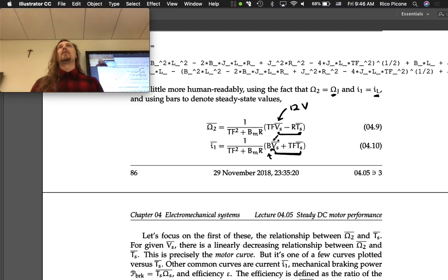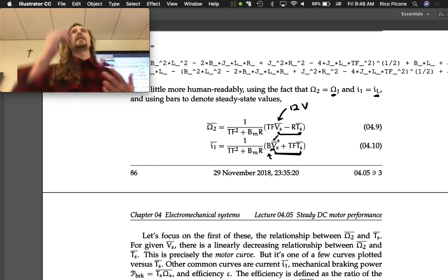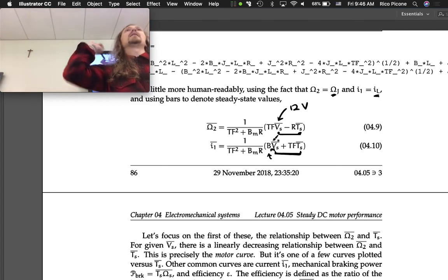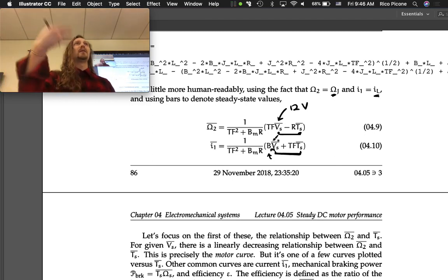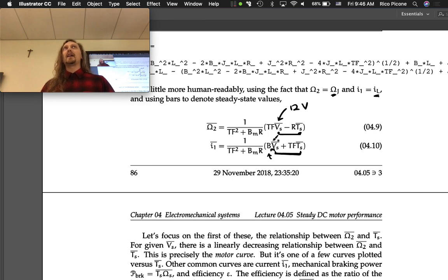So the brake will, but you're applying the brake as in your test setup. So the efficiency of the motor doesn't depend on the brake. The efficiency of the motor depends on how much energy is dissipated by the motor. And if you're running current through a wire with resistance, you're going to be dissipating electrical energy into heat, right?